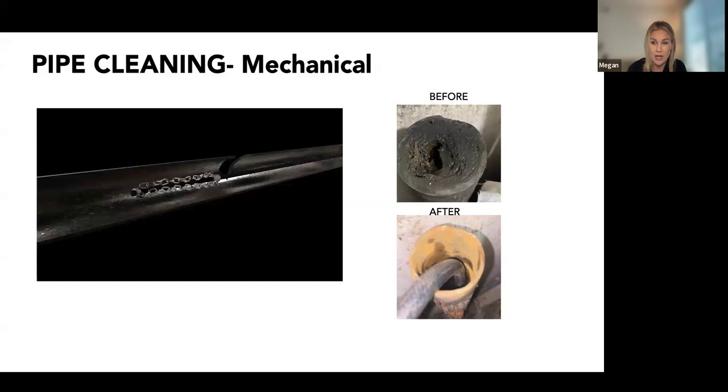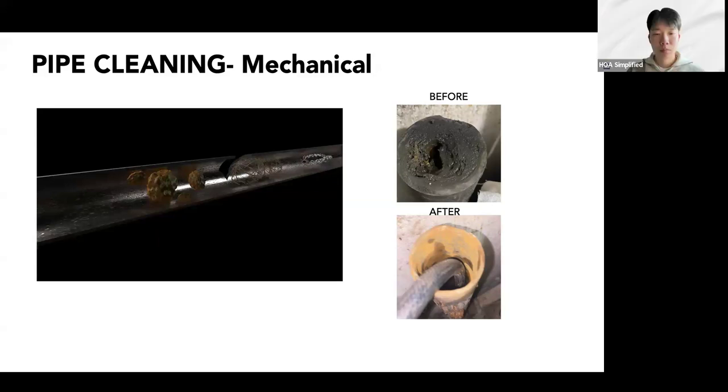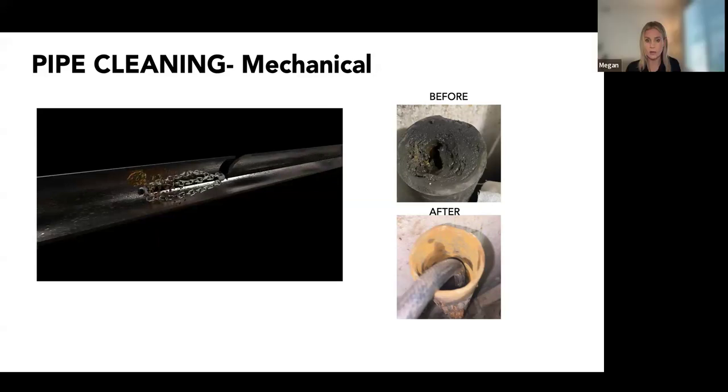They might not be hydrojetting, or the pipes are so bad that the jetting is making a little bit of a puncture within that debris, but it can't actually remove all of that buildup within the walls. It just kind of pushes an opening. If the buildup is soft like that, some of it might come out easily, but if there's a lot of roots or different things within the pipe, it might just make an opening and the problem will be relieved for a little bit, but then ultimately be present again not too long after jetting.